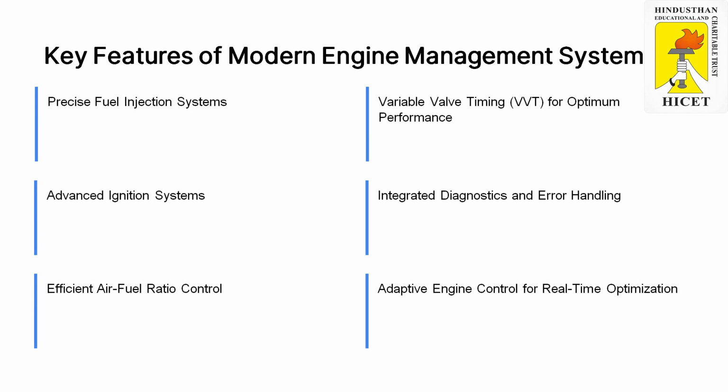While automobile vehicles are running, error codes can be generated, and these error codes and component failures can be identified with the OBD tool. It is an important and advanced feature in our engine management system, because in earlier days it was very difficult to identify the faulty component.